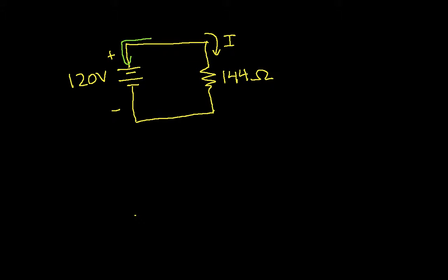This part of the wire that I'm outlining in green is all part of one node in the circuit. A node is defined to be basically everything that's connected by just a wire. And because we assume wires are perfectly conducting, there's no voltage difference between any 2 points along this wire. So the voltage here is the same, or there's no voltage drop between here and here.